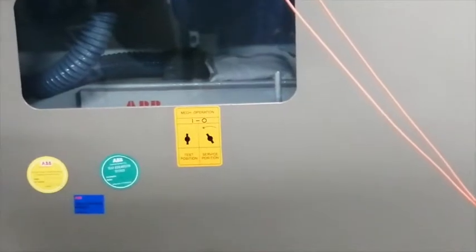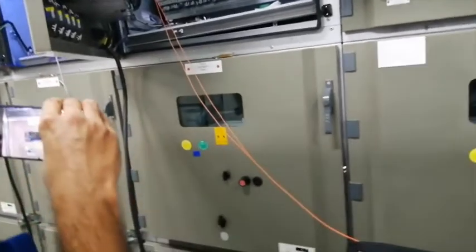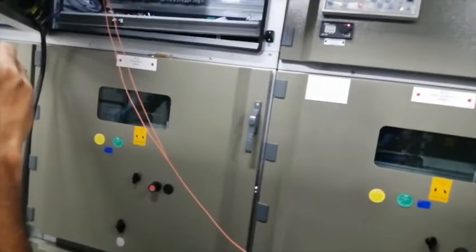Actually, in order to close the earth switch of 11 kV circuit breaker, as I showed you earlier, this is the hole to insert the crank of the earth switch. So in order to operate the earth switch of 11 kV circuit breaker, I have to rack out the breaker, the 11 kV breaker. As soon as I rack out the circuit breaker of 11 kV, I don't have the permission to close 132 kV breaker. So there is an indirect interlock between the breaker and the earth switch, and because of that I will not be allowed to close the 132 kV breaker.